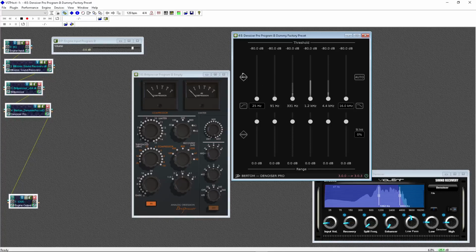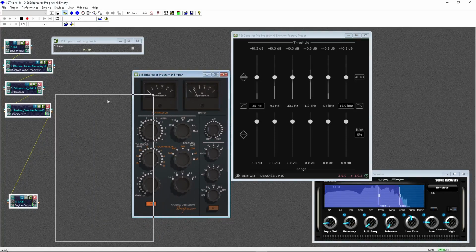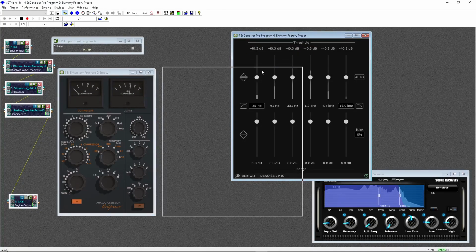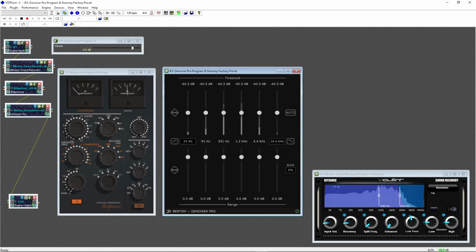Okay, I'm going to go ahead and bring these sliders up here. What you want to do on this is you want to set your frequencies. So what I do is I set this to around 3.6 and I just leave it there. I don't touch it. On the top end, I click in the high frequency roll off. And that will shut off all the frequencies, taper them off above 3.6 kilohertz, because what do you need to listen to it for? There's no audio there.